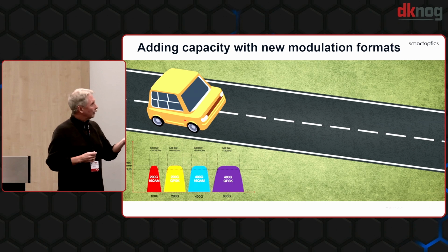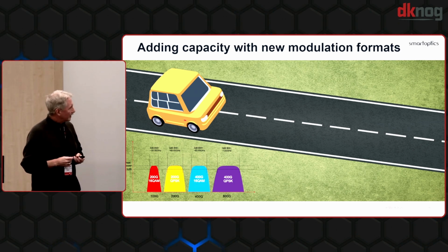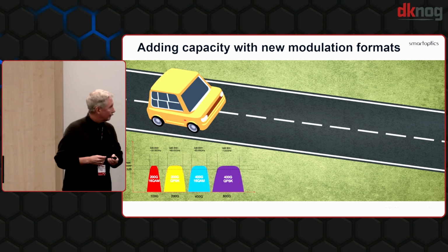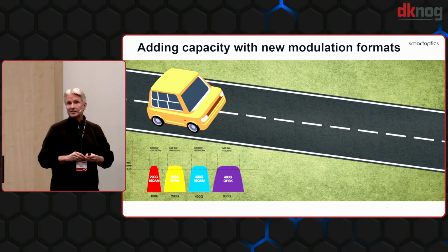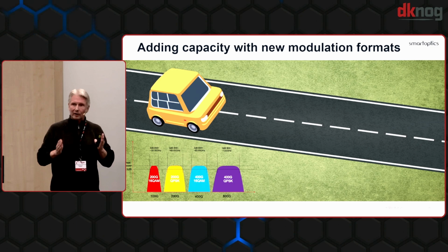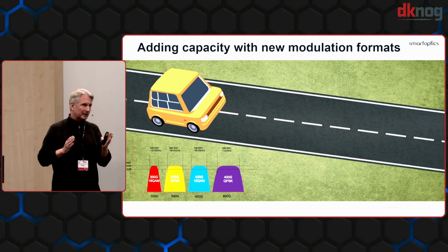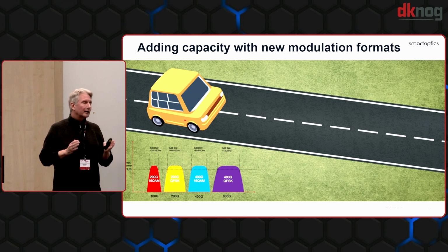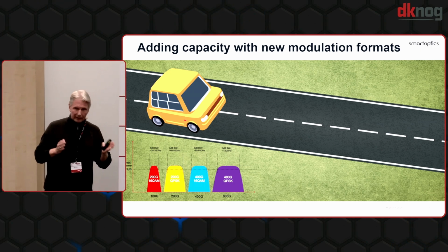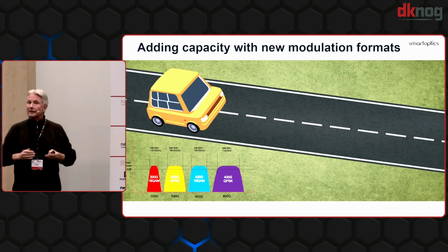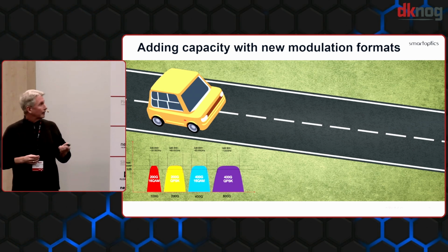So if we take the second one, 400 gig 16QAM, that's the standard 400 gig ZR or ZR plus optics. With that, you get a certain transmission capability, and it will use a certain amount of bandwidth, about 63 gigahertz of bandwidth. So then it will fit into a standard 100 gigahertz based DWDM solution.